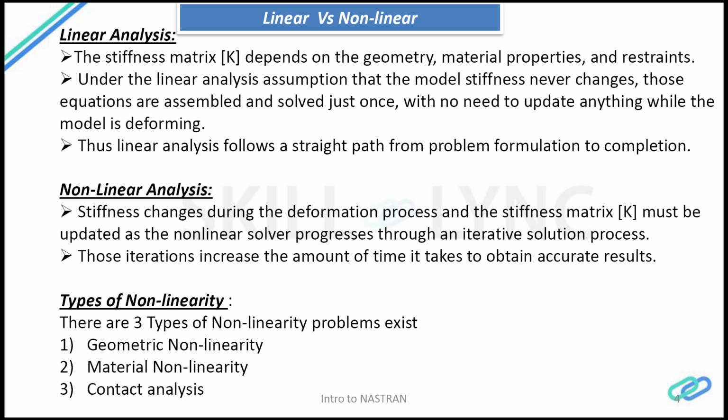So moving to the nonlinear analysis, you see the stiffness matrix which comes from the elements should keep on updating. It should get updated as the nonlinear time step or the nonlinear solution is in progress. So why is it the case?